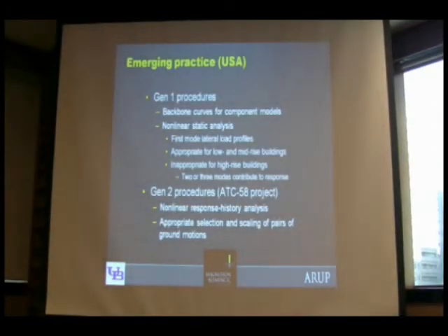With our Generation 1 procedures in the documents cited a few moments ago, we provide nonlinear force displacement relationships to enable the engineer to build models of structural components. And in the Generation 1 procedures, there was substantial attention paid to what we describe as nonlinear static analysis. So it has many of the features of static analysis that you perform at this point in time, but it's incremented static analysis, whereby we would impose a first mode lateral profile on the building, and then in essence we'd push the building to the point of incipient collapse.